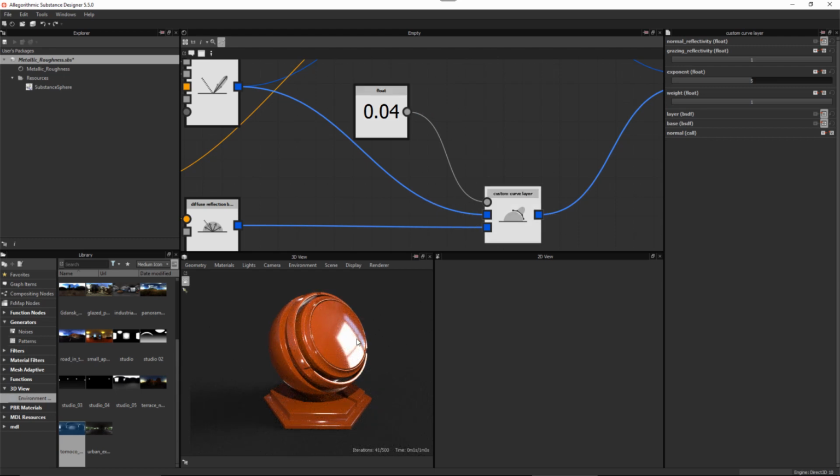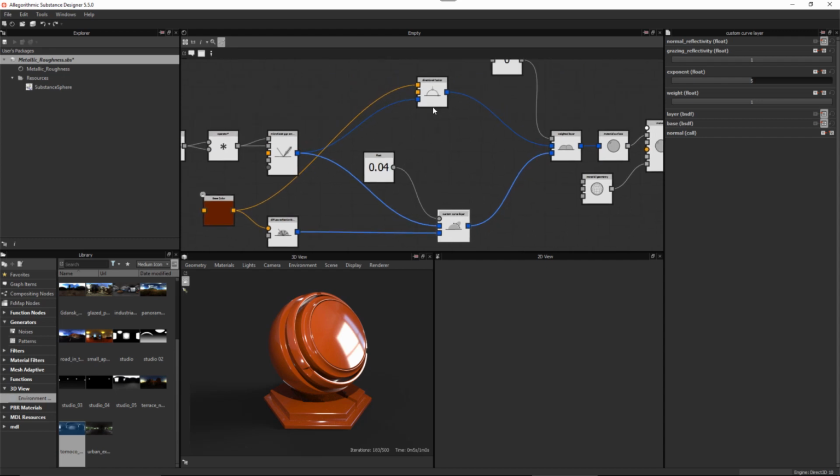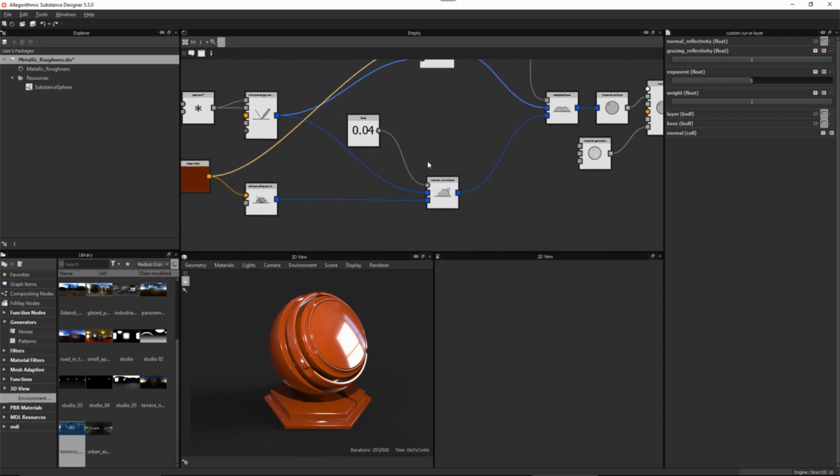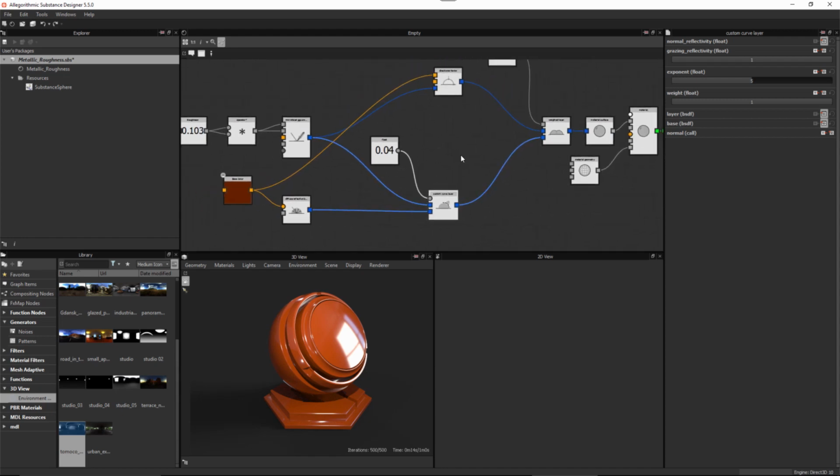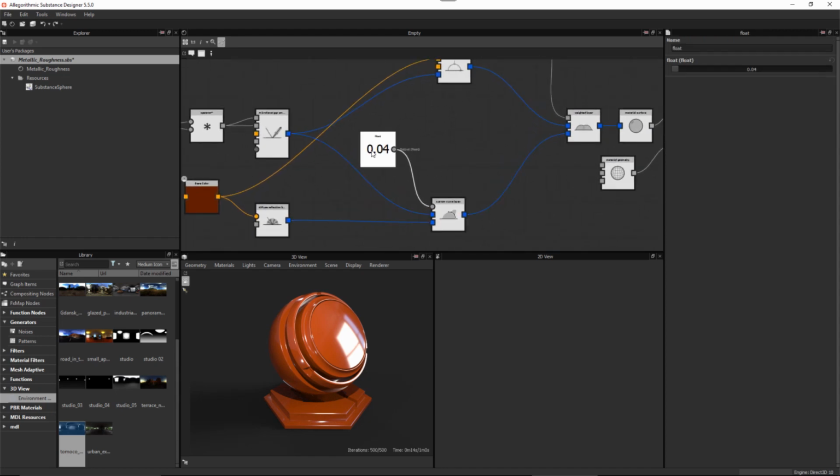And here you'll notice that, well, we get the same look that we had when we were using that Fresnel layer here with the 1.5 IOR. So here we basically have the same setup of metal rough shader that has a hard-coded 4% reflective value, that F0 value for dielectrics. But like I said, we really want this to be a user-defined parameter.